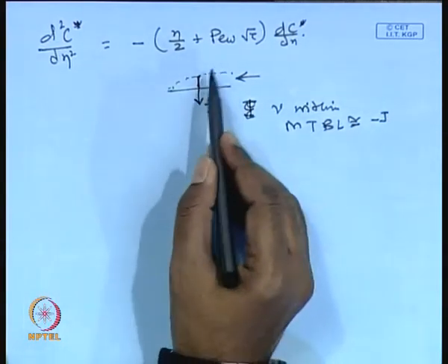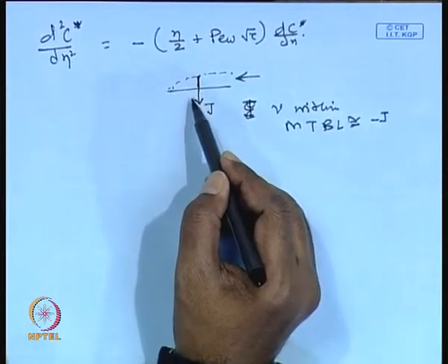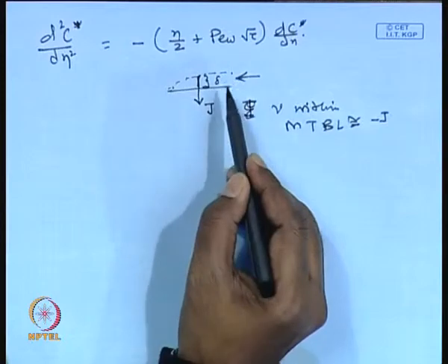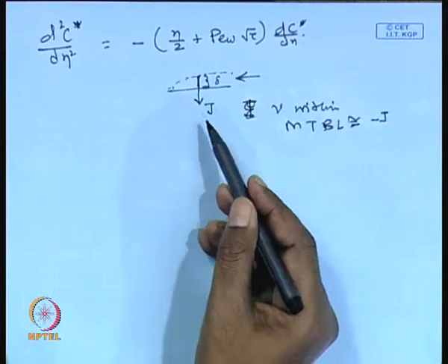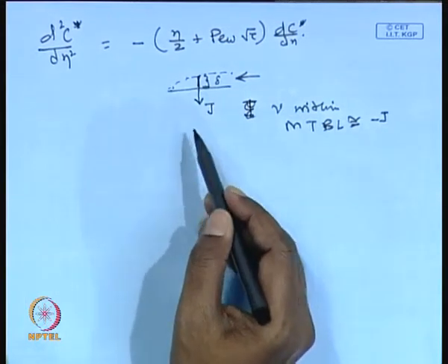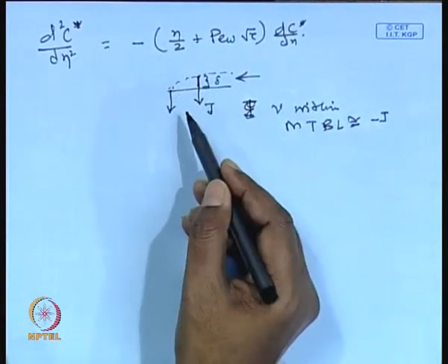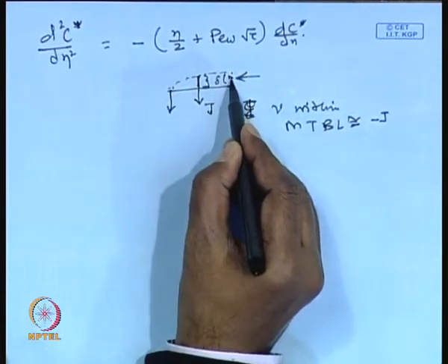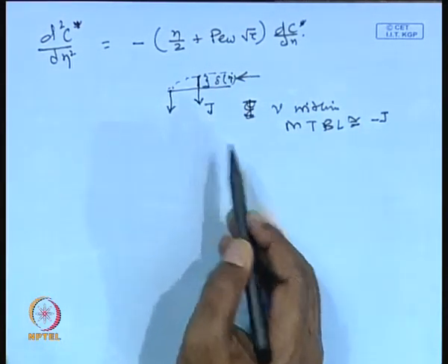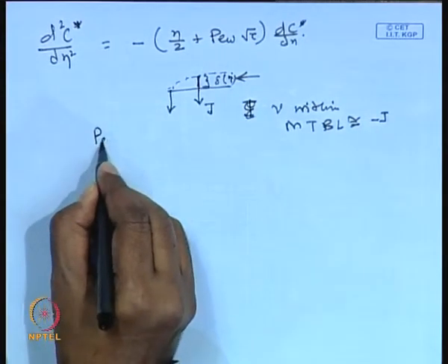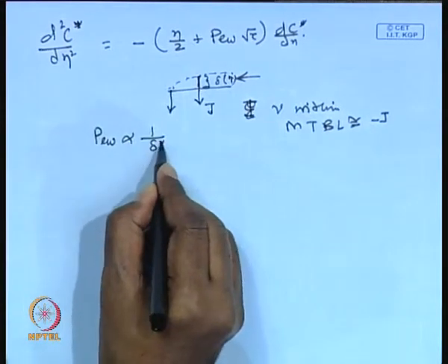And we have seen that this value of the permeate flux or the solvent flux will be inversely proportional to the thickness delta. The less the thickness of the concentration boundary layer, the less resistance it will offer against the solvent flux. So, you can expect a higher permeate flux at the beginning, at lower time. Now, in this case delta will be a function of time τ. So, when the thickness becomes more, the permeate flux will be small. So, it is inversely proportional to that. Therefore, non-dimensional permeate flux will be inversely proportional to delta star, okay.